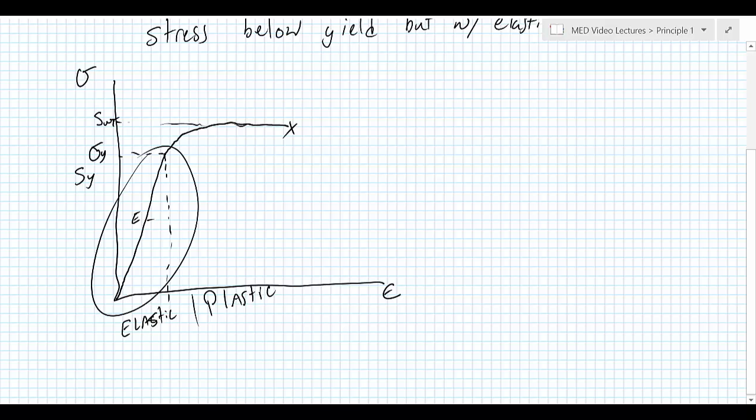But what's important to us is that we obviously know that a part fails once it hits its plastic yield strength. And we'll talk about static failure theories, which lead us to find, under certain stress scenarios, what that point is. But before we get there, we should consider what happens if it fails within the elastic region. There are two ways it can fail within the elastic region. It can either fail over time due to cyclic loading. That's the fatigue loading we'll look at towards the end of this first part of the course. And before that, it may deflect in such a way that it's bent too much to perform the operation that we want it to do.